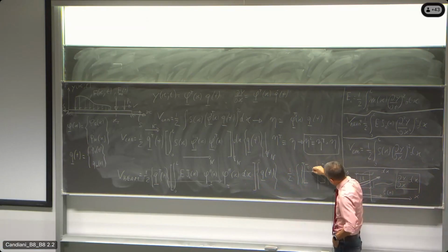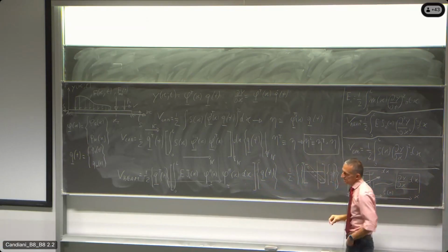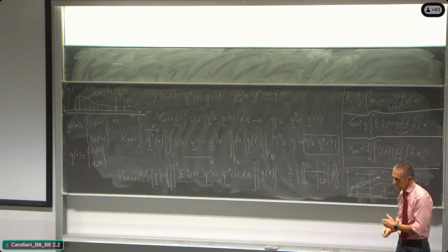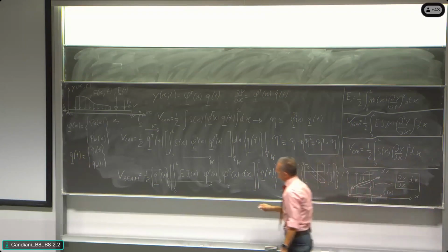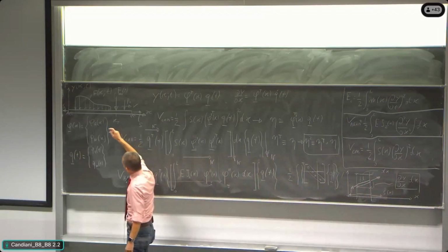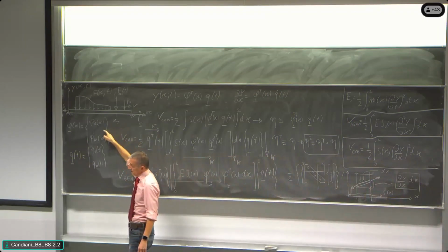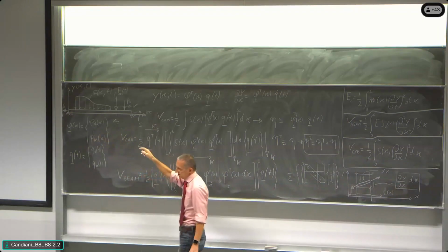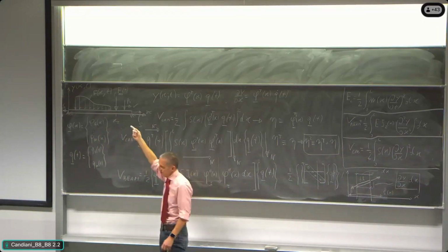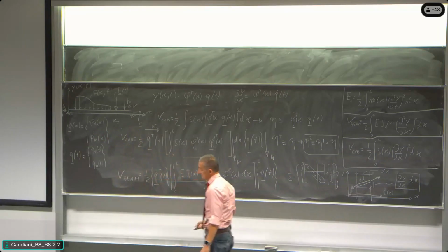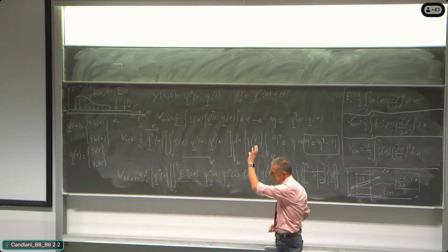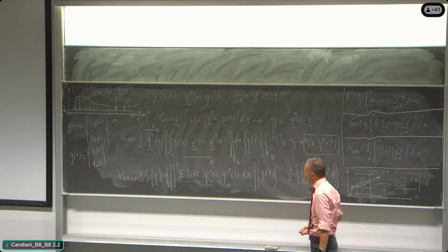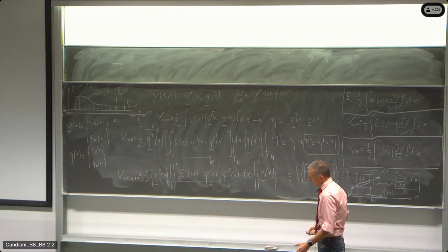We have just the i element; the ij element, in case i is different than j, is null, and we can demonstrate that the reason why they are null is because we are using, for the representation in principal coordinates, a very special base of functions. It is the base of functions that satisfies the partial differential equation that states the behavior of the beam. And we will make the demonstration.